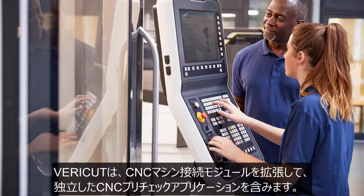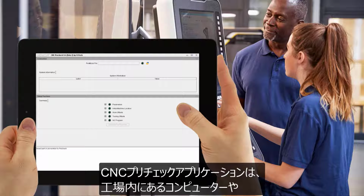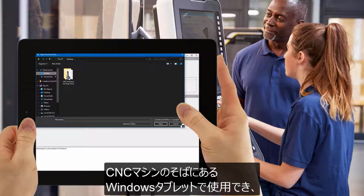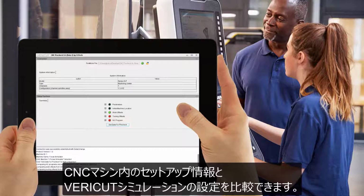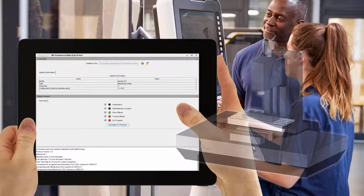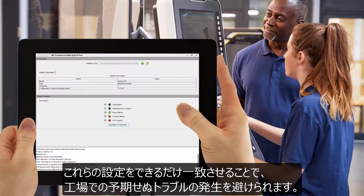VERICUT has expanded on the CNC Machine Connect module to include a standalone CNC PreCheck application. The CNC PreCheck application can be used on shop floor computers or Windows tablets next to the CNC machine to compare setup information in the CNC machine to the corresponding settings in your VERICUT simulation. By ensuring these settings match as closely as possible, users can avoid unpleasant surprises from occurring in the shop.